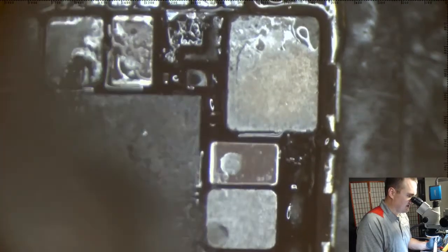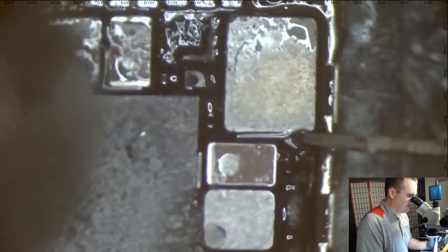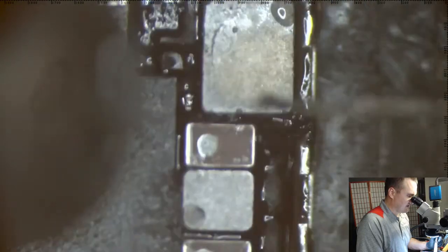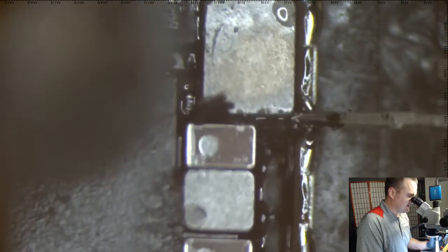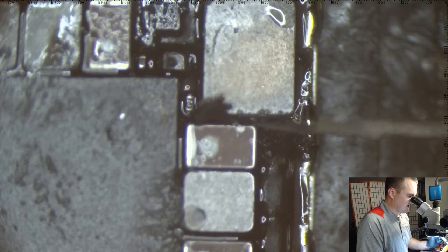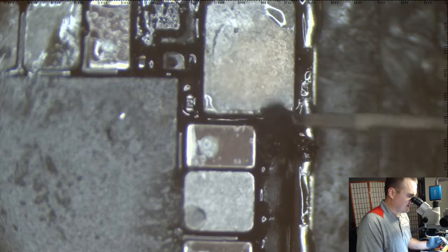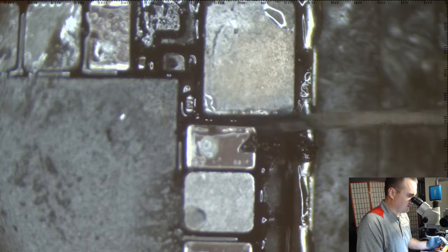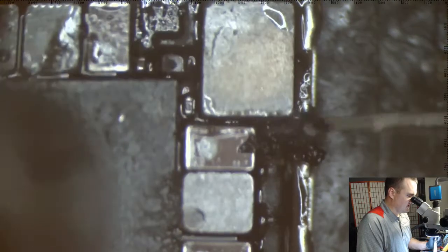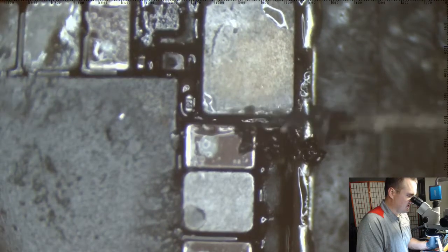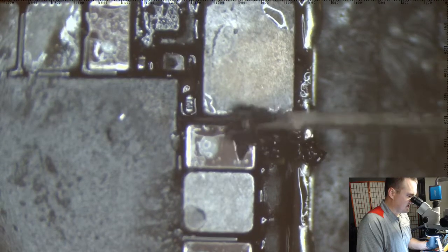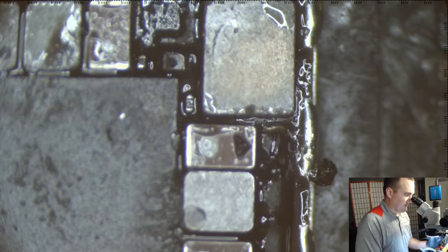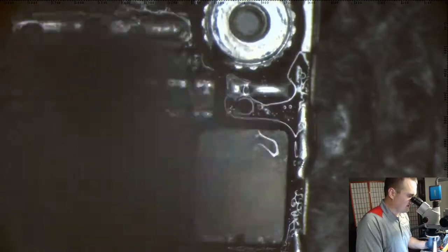You'll probably get on CPU, I want to say you usually get around a 70 or 80 reading. Likewise on GPU, it's very low. So I'm just hitting this underfill with air. That's really all we've accomplished up to this point, is removing underfill. It gets brittle. As you hit it with some hot air, it comes up a lot easier. Otherwise it has a real tough rubbery consistency to it.